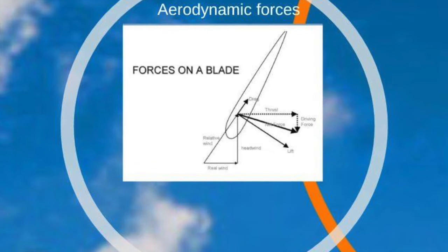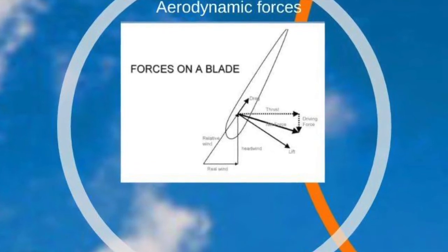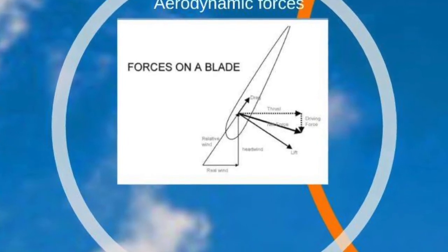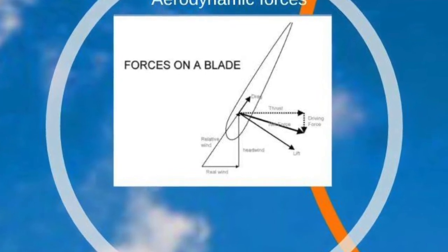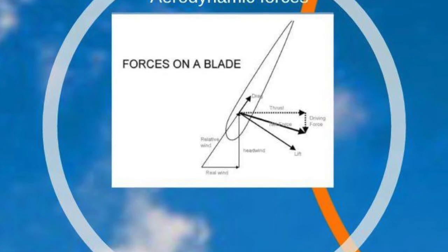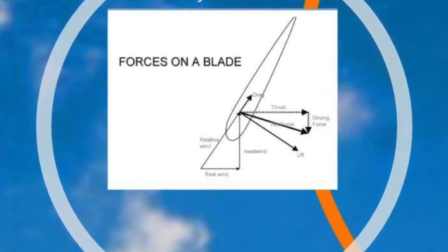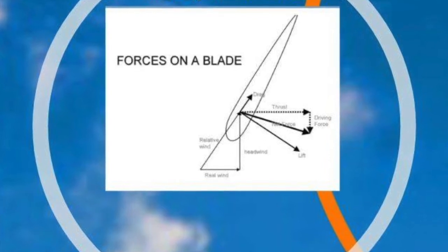Now let's consider the structural analysis of our blade. The forces which are of interest are the aerodynamic loads and the inertial loads. Using the blade element momentum theory, the blade is discretized into 20 elements. One of such elements is shown above, where the corresponding loads are accumulated. The lift and drag were then calculated, and the aerodynamic force was obtained from their vector sum.